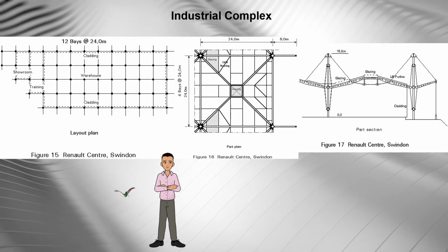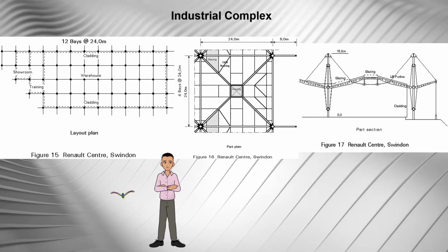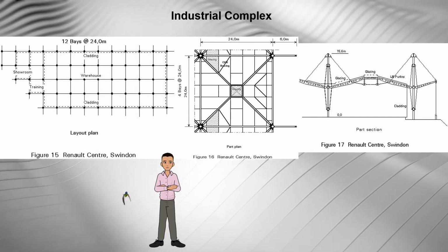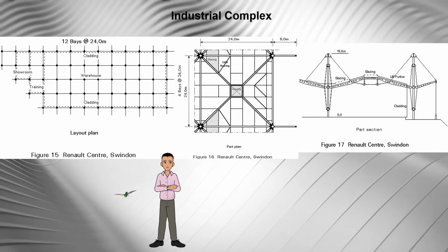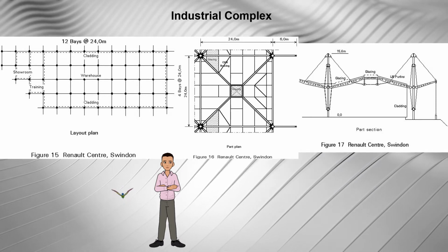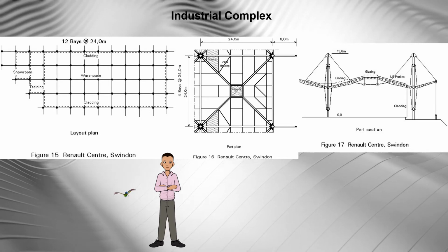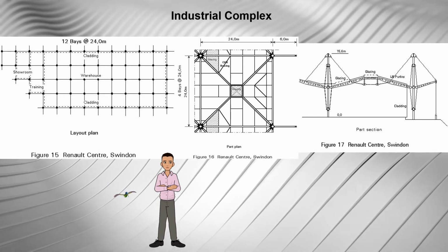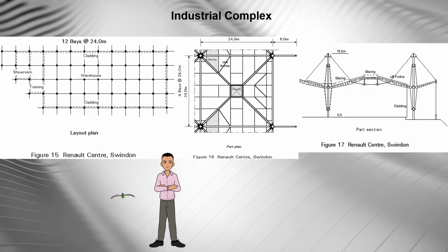Continuity between the main verticals and the trusses is established by rod bracing connecting the heads of the main verticals to the quarter points of the trusses, while the internal verticals are balanced by trusses on each side. The perimeter verticals, which have transverse and diagonal trusses on one side only, are balanced by ground anchor bracing, short beam members connected to the verticals at the same level as the trusses.